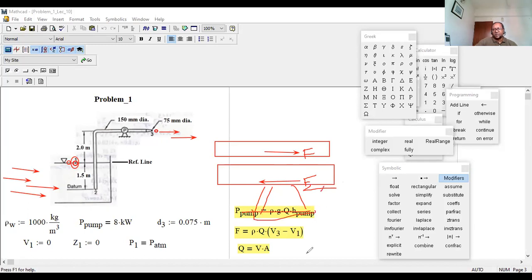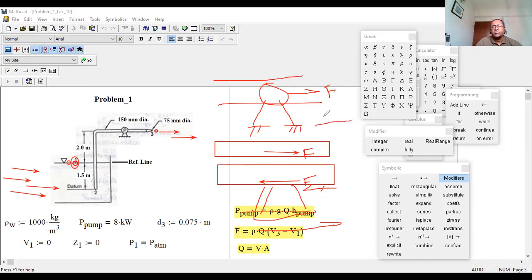But what will be at the bottom then? At the bottom it will be along this direction, right? So you see, you have this support, say supporting your pump with two angles, right? Inside the pipe the force is working along this direction. You think the other way. So how can we balance it? Right here, the fluid force is working to the right. So how much force will be in the support? It should be in the opposite direction, right? So this will be the reaction force F. That is enough.